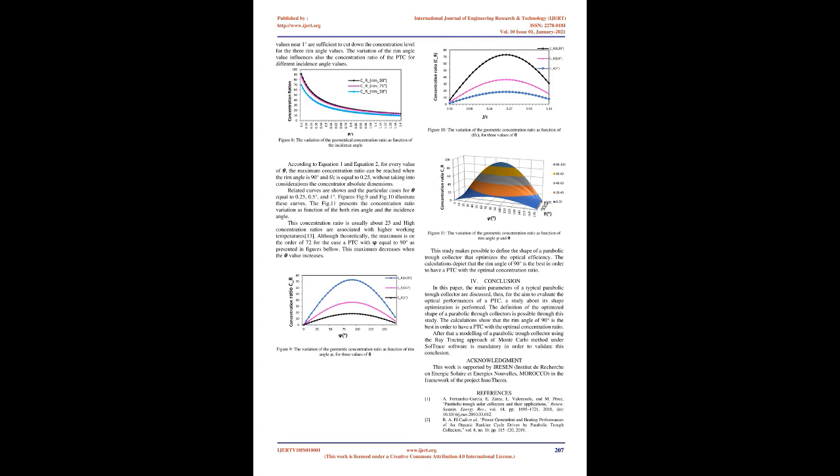3. Shape optimization of a PTC, geometrical considerations. From an optical point of view, light is considered as rays carrying power through a transmission medium and interacting with reflective and diffractive surfaces. The definition of the concentration ratio of the parabolic trough collector takes into account a cylindrical absorber that is fully hit by the rays reflected from the mirror. It is clear that the CR becomes lower when the incidence angle increases.